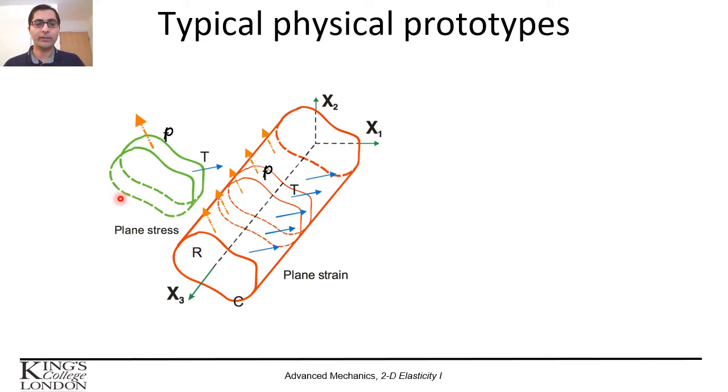These are two diagrams for the two cases. See, we have here a slice that describes the plane stress. Assume that's a slice from a cylindrical or a spherical body. The body forces P and the boundary forces showed here by T, the traction force, they're symmetric.